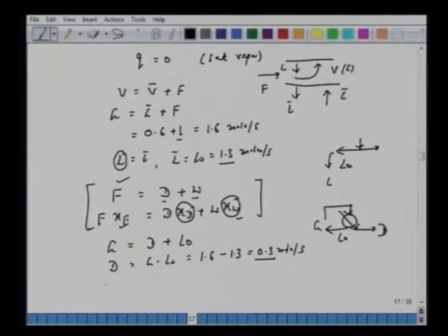How about for the bottom column? We have L bar split into 2, W plus G bar. So W equals L bar minus G bar. L bar we set the same as L0, 1.3. G bar is the vapor sent back from the reboiler as reflux vapor, which is 0.6, so W is 0.7 moles per second. So essentially now we have all the quantities.